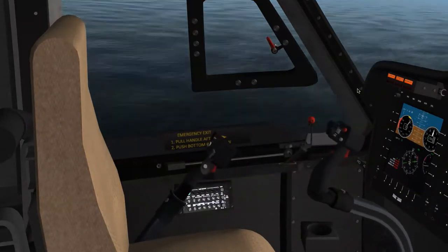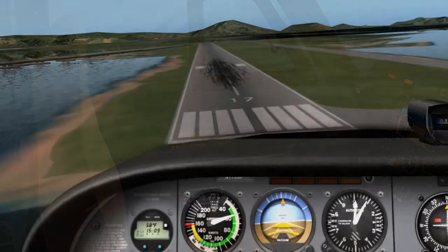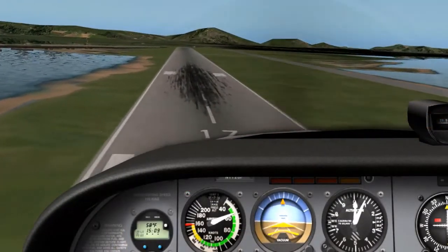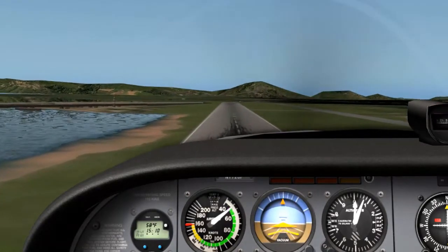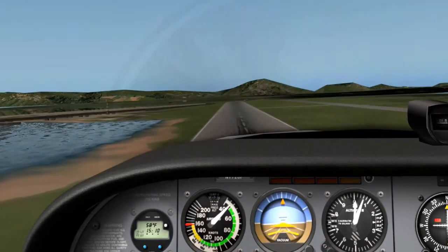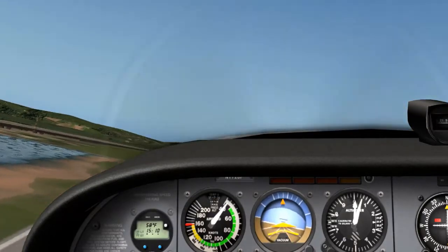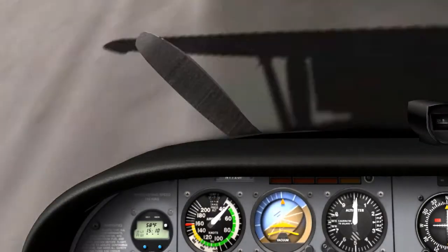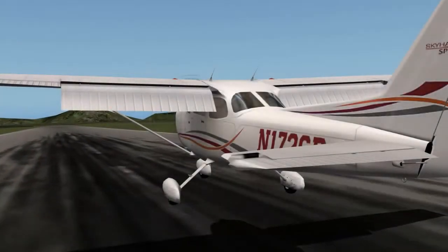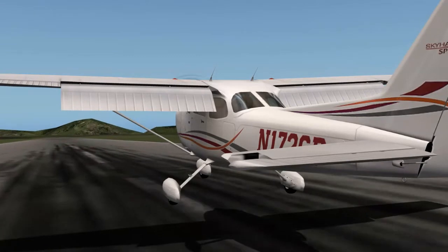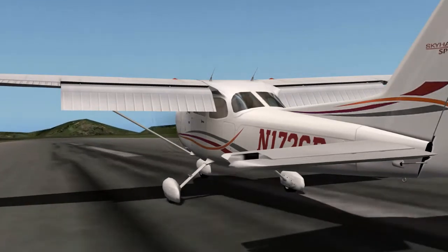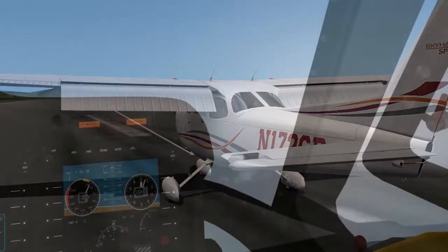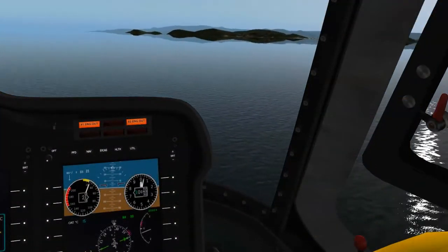So it's really a lot like landing in a fixed wing aircraft. You don't want to flare so high above the ground with the engine pulled back to idle that you stall at 50 feet and then just nosedive into the runway. You want that stall, when you hear the stall warning horn go off and the wings bleed off whatever lift they have left, to occur at maybe 1 foot above the ground, so that the wheels then softly touch down. It's really kind of the same thing here.